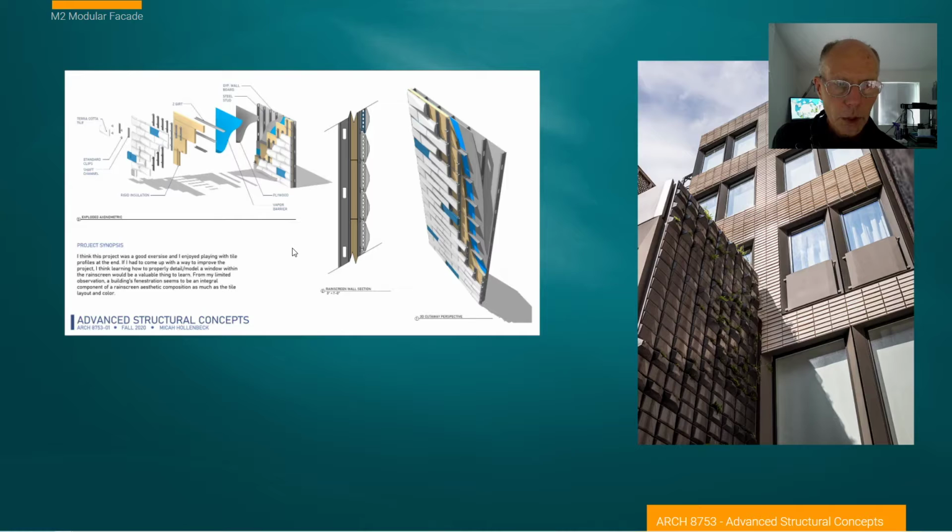One of the reasons I wanted to bring it up and discuss it is that these extruded tiles really don't have the ability to create dimensional curvature in two planes. This tile is curving in a triangular form where it starts low and goes high, and that can't actually be done in a conventional extruded clay tile. I didn't want that to be accepted per se in the application as I was presenting it. There's really inherently nothing wrong with this type of tile system. What is the issue is how it would be manufactured.